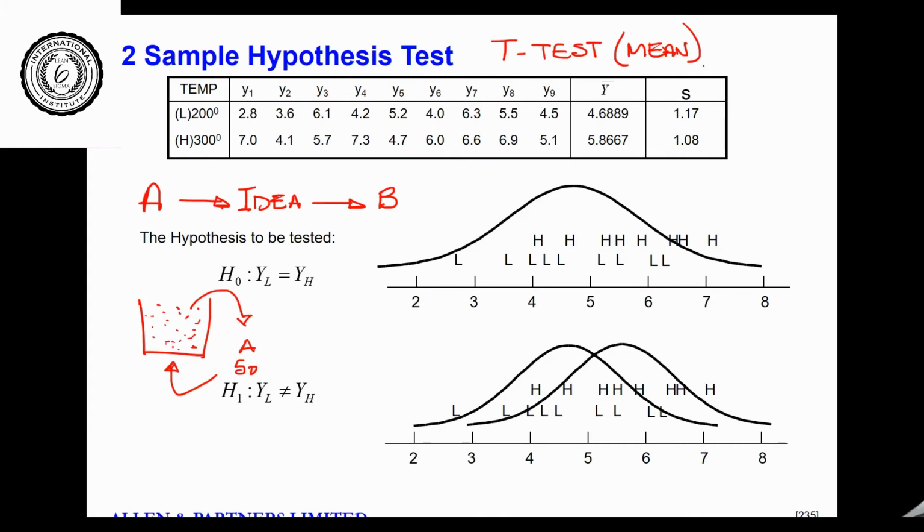But if you took another sample out of the same bin, so now we'll take sample B, another 50, when you measure the same feature and you work out the average result, would you expect to get an identical set of results? Or an identical average even? Well, no, of course not. It's two samples. So you see, one of the problems with suggesting that when two samples are different, that is the indication of a shift in the process.